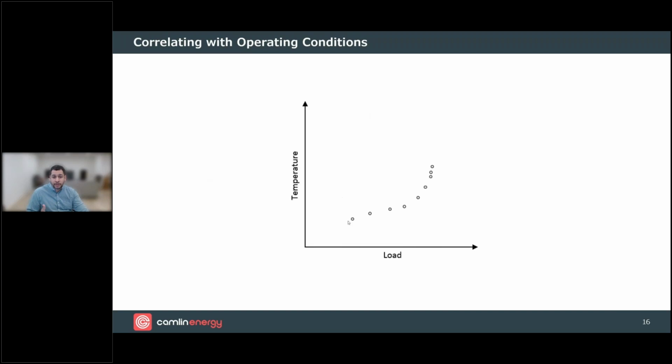It takes quite a while for machines to thermally stabilize in some instances, and going through that regimen from low load to high load, waiting for temperature to stabilize, will require some augmentation of other units at the plant. Juggling load between units to ensure that you go through these transition points and take these measurements can be very impractical in a periodic measurement.